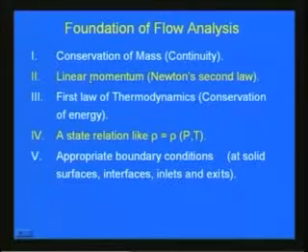The five important foundations are the conservation of mass, based upon which we derive the continuity equation; the linear momentum, where based upon Newton's second law we derive the momentum equations; the conservation of energy, where from the first law of thermodynamics we derive the energy equations; the state relationship between fluid properties like pressure, temperature and density; and lastly the appropriate boundary conditions at solid surfaces, interfaces, inlets and exits.